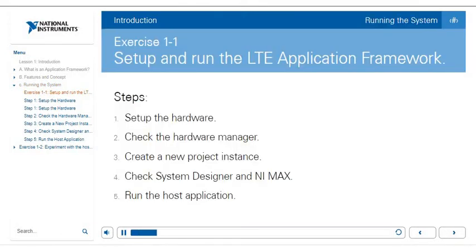Exercise 1.1. To set up and run the LTE application framework, you need to follow 5 steps. First is to set up the hardware. 2 is to check the hardware manager to make sure everything is properly connected. 3 is to create a new project instance. 4 is to check System Designer and NI MAX. And then 5 is to run the host application. Let's walk through these steps together.